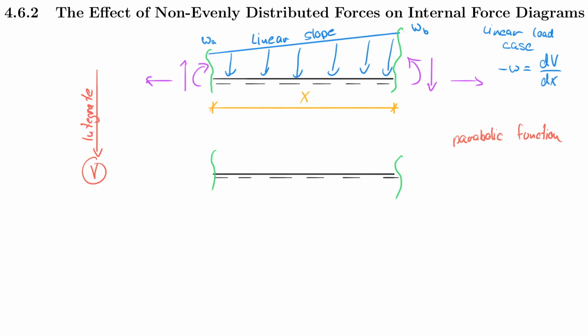To clarify that better, let's bring in our 3 or 4 distances again. So let's say here I have xA, then here I have xB, xC and xD. And maybe to better communicate that, let's change this up here to wD now, so that we understand that that relates to each other. But what I can do now is I can say that this value here relates to the slope of the shear force function. And so I have a small value there, and don't be fooled, it looks like it's positive, right, because we are above the dashed line, but keep this negative in mind. So sometimes when people see this negative, they just want to draw a negative function here, but it's the slope that is negative.